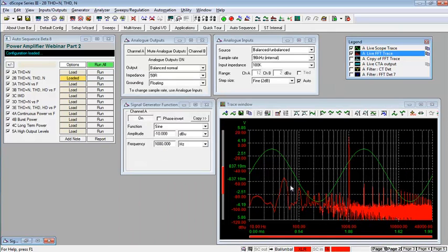If we go to my FFT here, we can indeed see that there is a fairly pronounced amount of low frequency mains noise visible here. I'm in Europe, so this is a 50 Hz signal plus its harmonics there. Now this could be down to a number of possible issues. There could be a design problem with the power supply. There could be poor power supply rejection in the amplifier circuitry. We might have a ground loop in the measurement setup, for example. So not a problem with the device under test in itself, but a problem in the way that we've wired up our device to the measurement system.